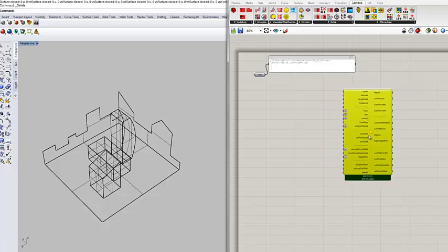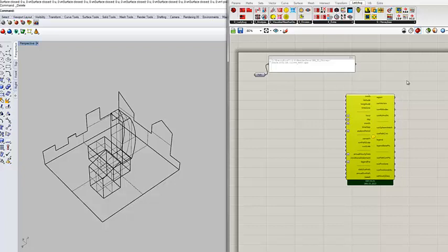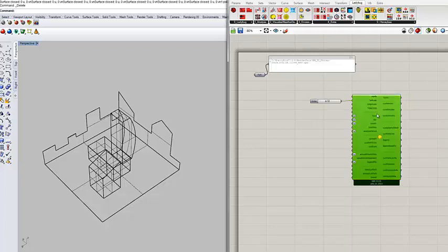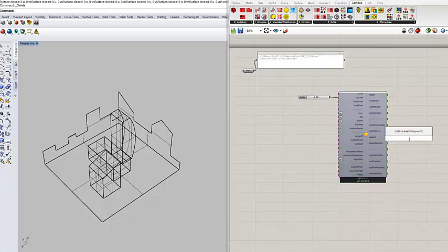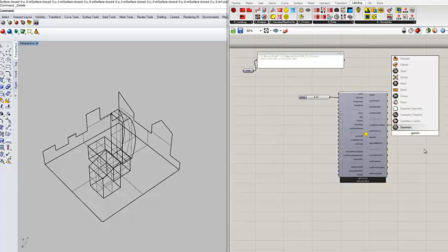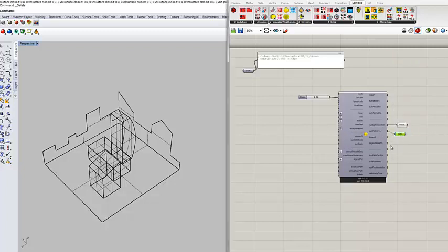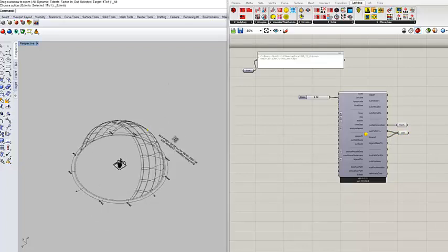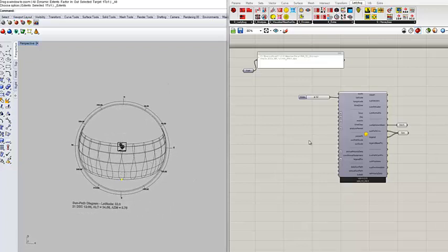You can grab it and bring it here, and what you need to have a sunpath is basically the latitude of the place. So if I import the latitude, like just so, and I need to visualize the results, so I get a mesh here, I connect the sun mesh, and then a geometry, and then connect the rest of the outputs here, like the ones that I want. So if I zoom extend, you can see the sunpath here, and the data here is already set as default, so that's why you get the sun too.